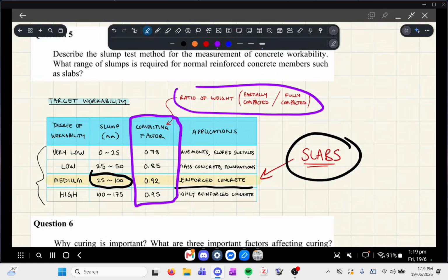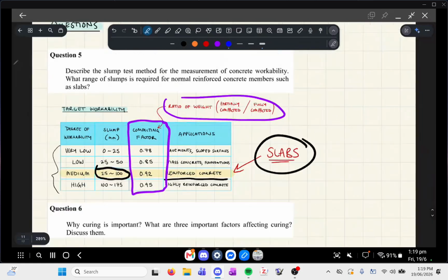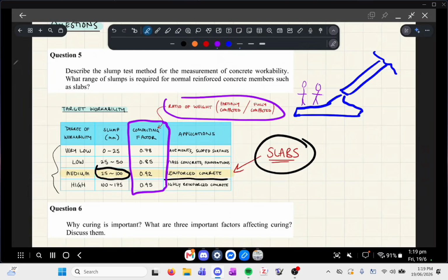I don't think I really mentioned this last time either, but as you pour concrete, you've got your boom pump, let's say, spewing out your concrete. You'll have some workers on the other side with various tasks. These are the concreters, and they will always have at least one person who does the concrete vibration with a concrete vibrator. This is like a little stick thing, and it vibrates the concrete, pops all the little air bubbles, and makes the concrete more uniform.